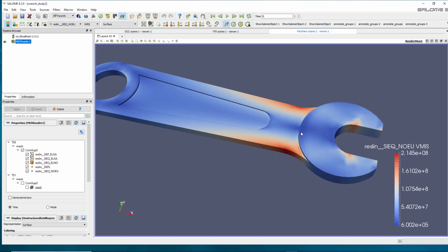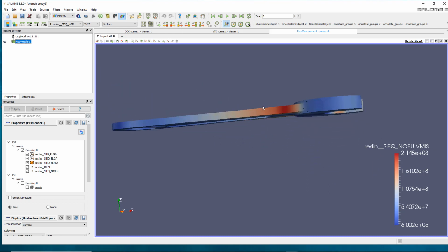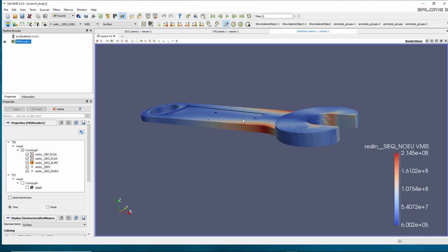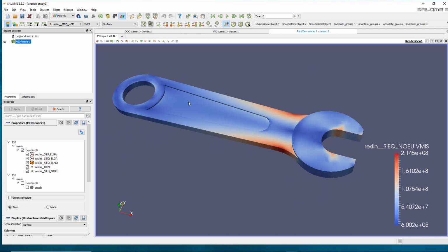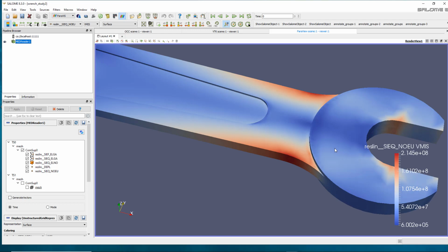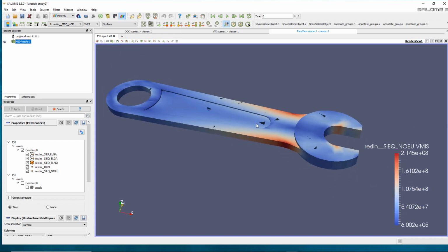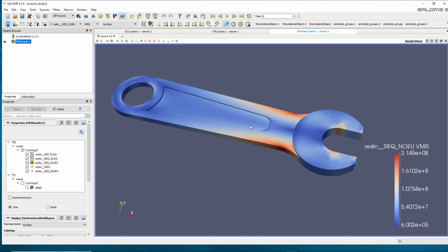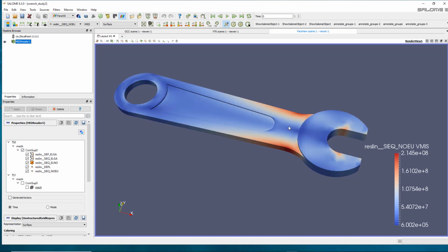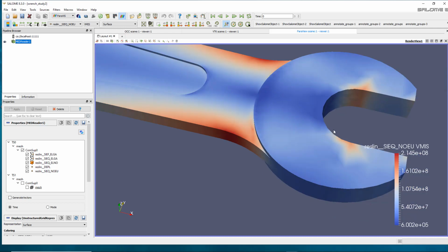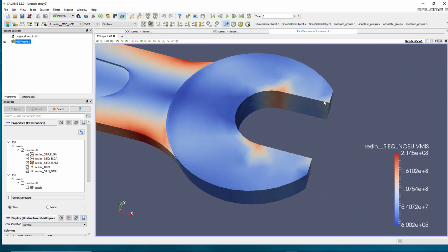So of course, this mesh is very coarse, so I would not think that this is the right solution. This is probably not that great, because calculating stress requires small meshes, much smaller mesh than the displacements. So generally, even with such a coarse mesh, your displacement might be accurate, but your stress will probably not be. Especially if you look at this area here, that's a bit strange. You know, I fixed that, and I don't know why I have something like that around this.